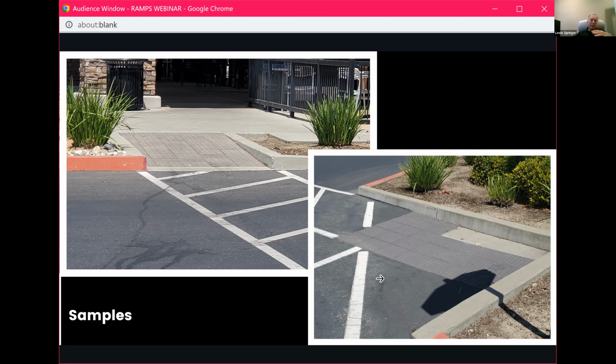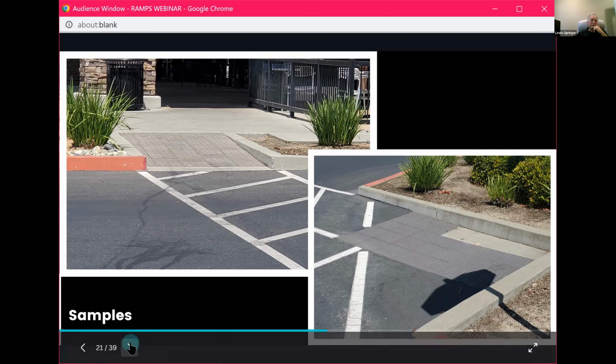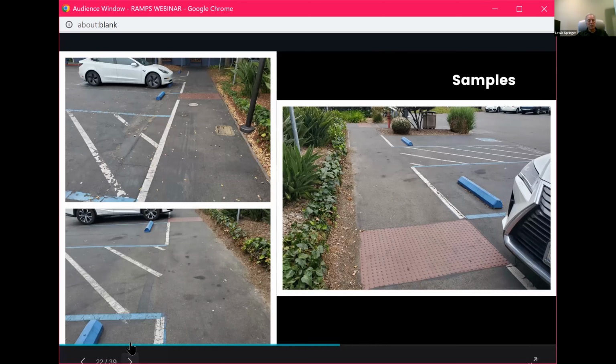So like I said, if I were to write the report on this curb ramp, I'd actually recommend removing it and replacing it with a detectable warning that has a contrasting color. And in today's codes, it really says that all detectable warning has to be yellow. There are some exceptions. If you're replacing only a small percentage, then you can maintain the existing color, but the color has to be a contrasting color.